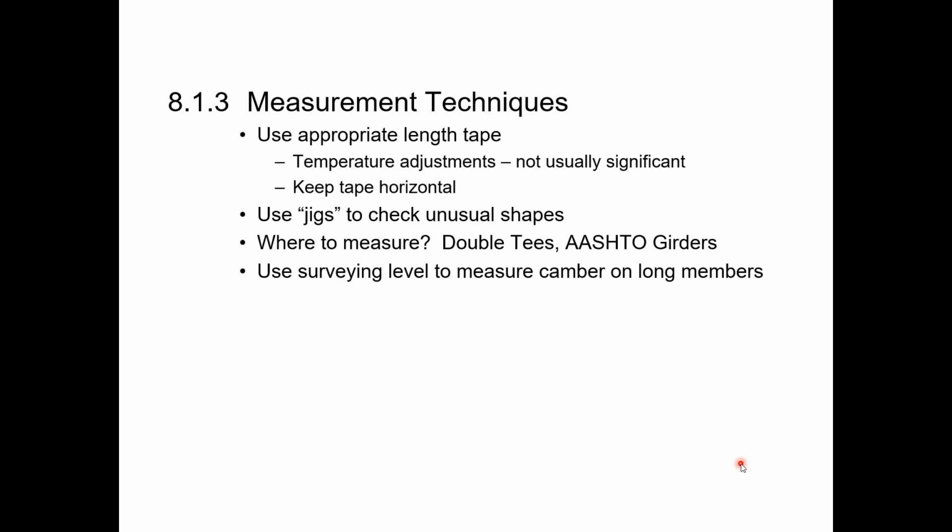The other difficulty that comes in with things like that is sometimes those tolerances, and actually in most instances that I'm aware of, those tolerances are much tighter than what PCI would even allow, sometimes to the hundredth or tenth of an inch. And so you have to be very, very accurate with your placing procedures and your form work and all of that. Otherwise, you spend a lot of time and effort and end up having to scrap a piece because it doesn't meet the tolerance requirements.